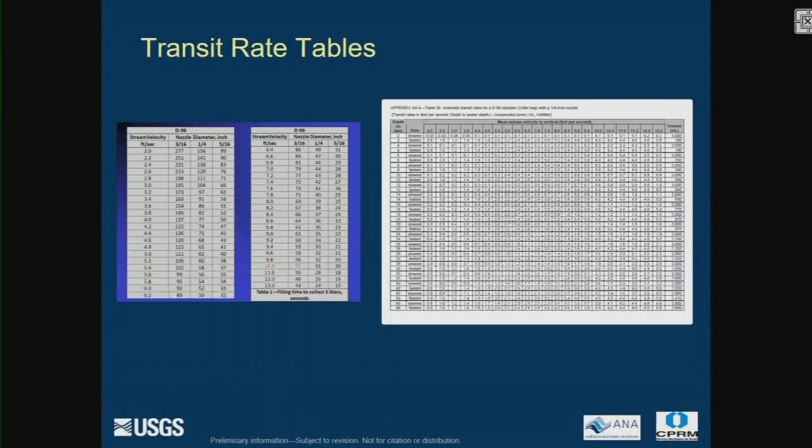You may want to limit that, so you may not want to collect 2,800 milliliters. You may only want to collect 1,000, maybe. This will allow you to adjust those rates, because we composite some of our samples, and our compositing containers for our water quality, our churns, are limited by the volume, so we have to be careful how far we go up the ladder with our rates.